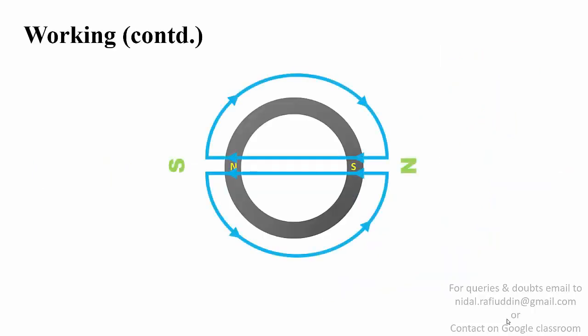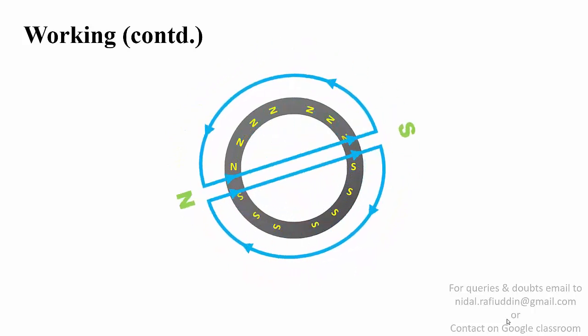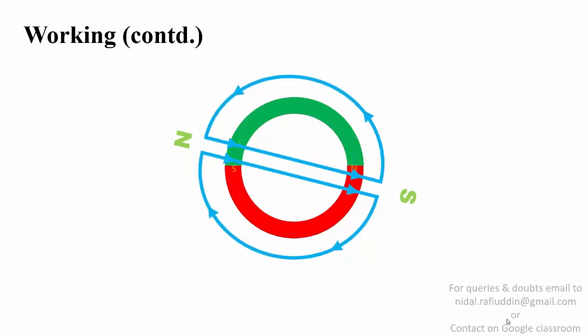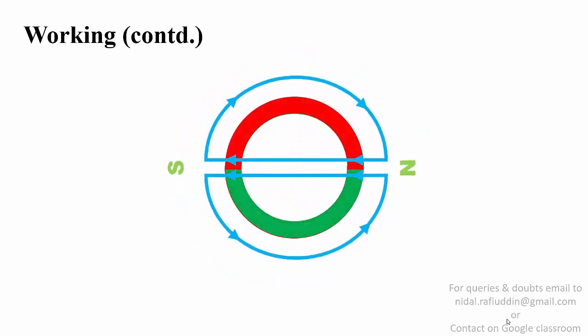Now, using this knowledge, when the rotating magnetic field traverses along the rotor periphery, which is initially unmagnetized, it causes the rotor to develop residual flux, or in other words, magnetizes it. During a half cycle of the rotating field, half of the rotor periphery becomes north, while the remaining half becomes south. These induced poles then experience attraction towards the rotating field. When the rotating field moves further, it causes a change in the polarities of the rotor. This phenomenon allows the rotor to experience continuous torque. Notice that once the rotor achieves synchronous speed, the rotating field no longer sweeps the rotor, and hence the polarities of the rotor will not change, and the rotor gets locked with the rotating field.